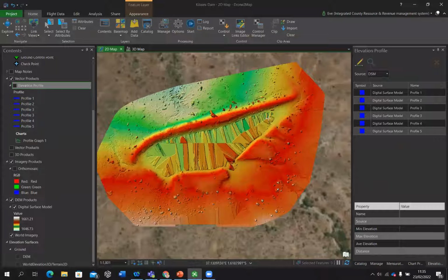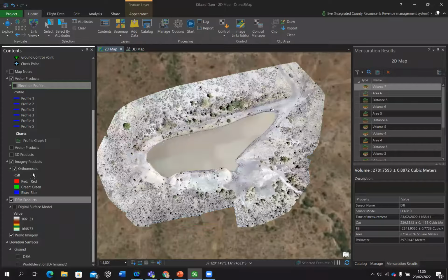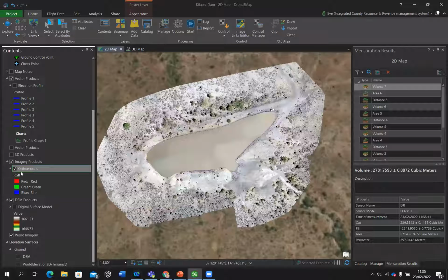Apart from that, it's also important that when you're working on your data, you're able to share this information with other members of the organization. As I mentioned, our drone solutions are integrated with the platform, and they allow you to connect to ArcGIS Online as well as ArcGIS Enterprise. So you can always share your information to either your ArcGIS Enterprise portal or your ArcGIS Online. For instance, if I want to share the orthomosaic that I created, I'll simply select the output and then come to share.